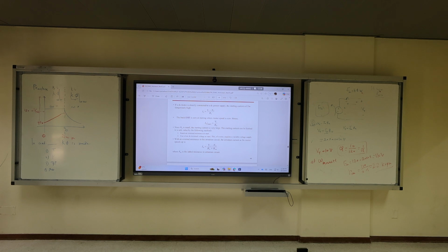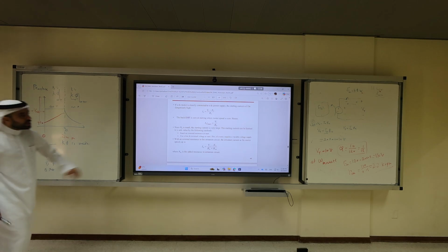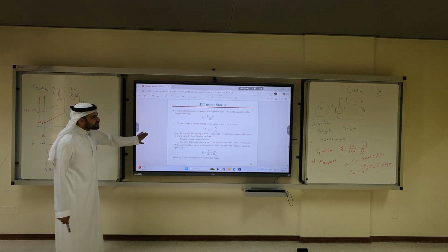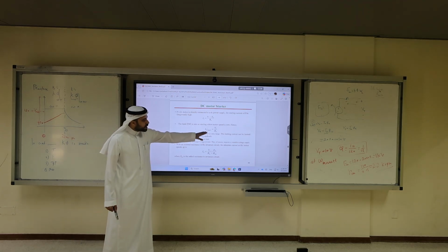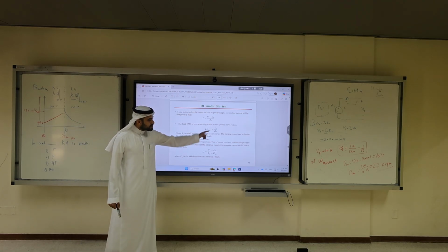Yes. And what's the solution we just made? Gradual voltage. Reduce the voltage using power electronics. So the issue here is, I'm not going to cover it much, but DC motor starter, the inrush current is very high unless you reduce the supply.